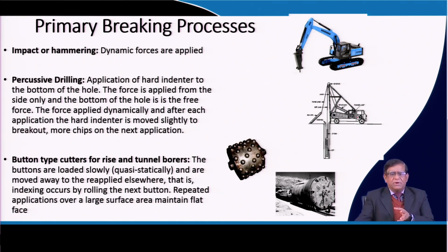The same principle, when done in a mechanized manner, is called cable tool drilling. You can study these machines later, but with percussive drilling you have to use very hard rock. Sometimes a high carbon steel bit is thrown from the top, and by that they do the drilling. So, this is percussion drilling.